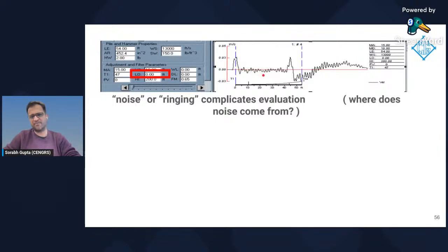Now, why does this ringing happen? I don't know. My guess is, more likely, the pile top surface was not prepared properly. Maybe it was not cleaned or ground properly. And if you test on loose formation, sometimes when you impact the hammer, the accelerometer will vibrate a little because it's not properly fixed to the pile head. It could be that. It could also be that you have long rebars sticking up. So when you impact the hammer, there is low strain vibration in the reinforcement bar. And that, as I told you earlier, will show up in your PIT results.